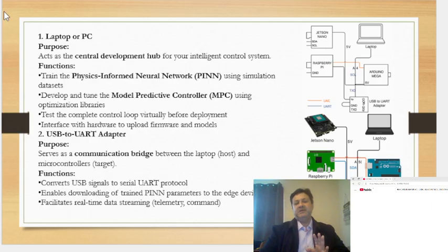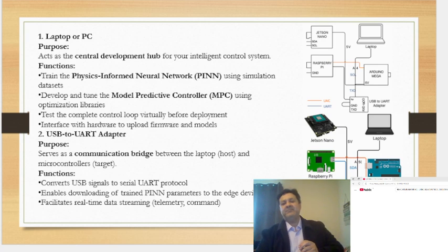So through USB to UART adapter, these files or serial commands are transferred to the Arduino STM. So I'm talking about this thing, right? And these are the sensors, voltage, current, and all that. So voltage level, as I said, will be this, and the constraint is if Jetson and Arduino differ in logic level, right? One is, let's say, 3.3 volts, another is 5 volts. Use a logic level shifter to prevent damage. So then there is an issue.